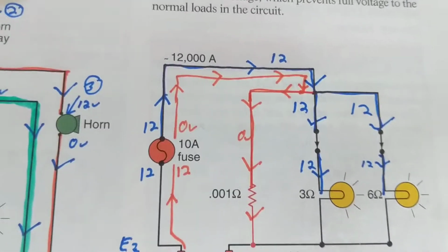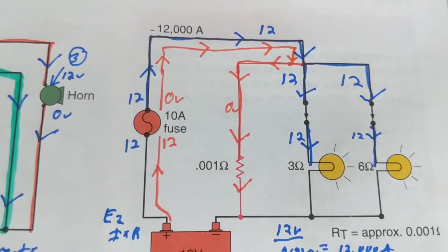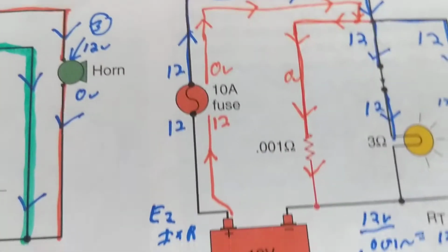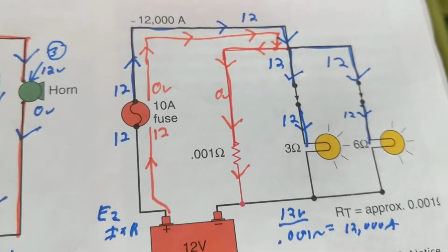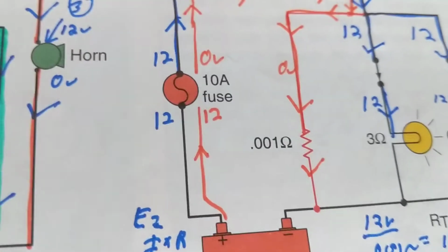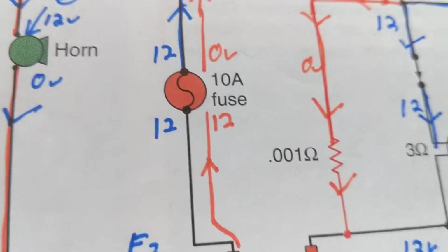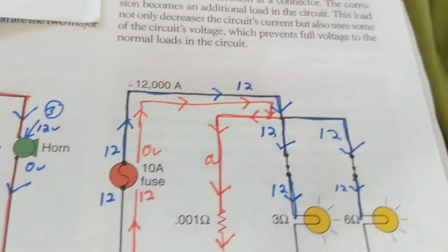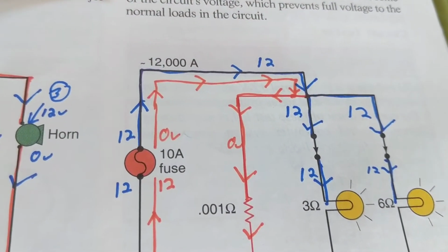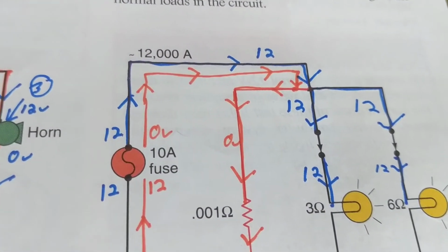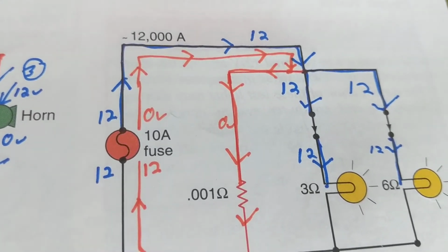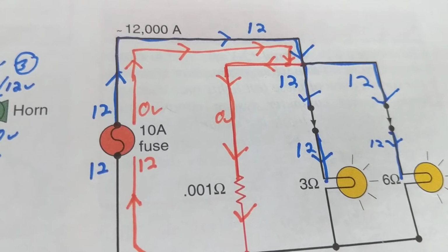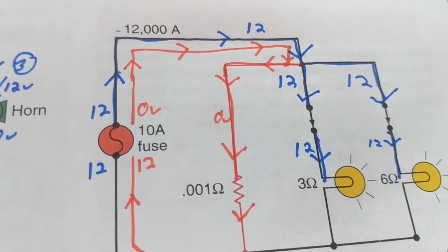Okay, now I'm going to make another video, because I got a message from someone asking about a TPS sensor, and I'm trying to get a schematic for that. Remember, when you adjust TPS sensors, they have to be accurate. If it's supposed to be 0.3 to 0.4 or whatever, depending on the make and the model, check the manual. Don't leave it up to your own discretion. Check the manual for how much you have to adjust it, with the 4 wires.